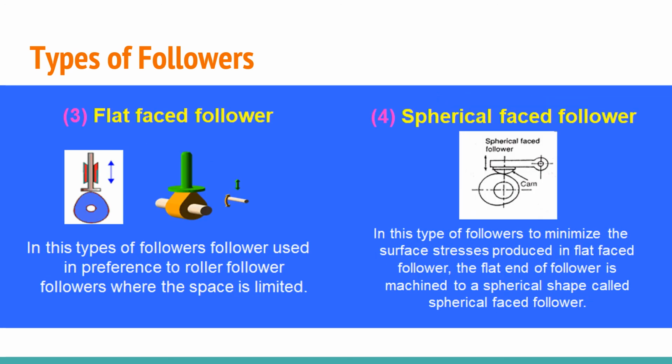The next is flat face follower. In this type, the follower is used in preference to the roller follower when space is limited. In this case, there will be a constraint that the distance between the cam and follower must be very minimal.